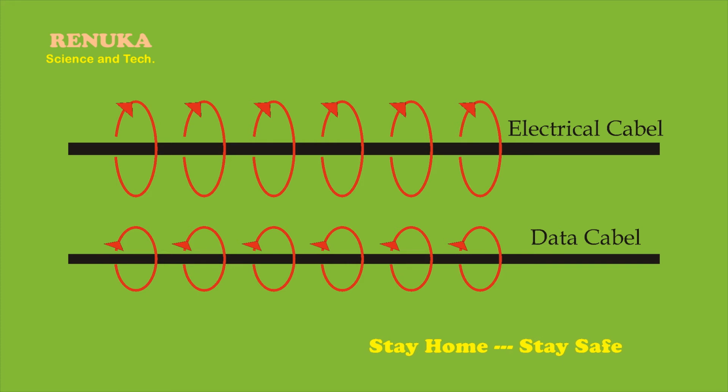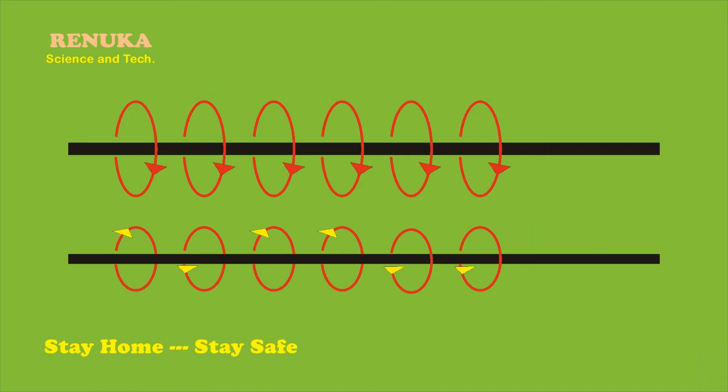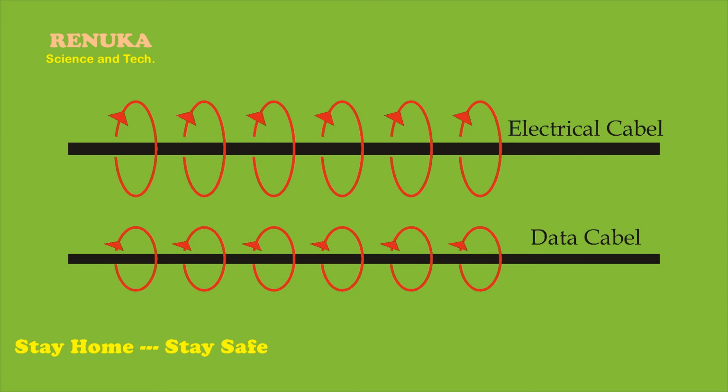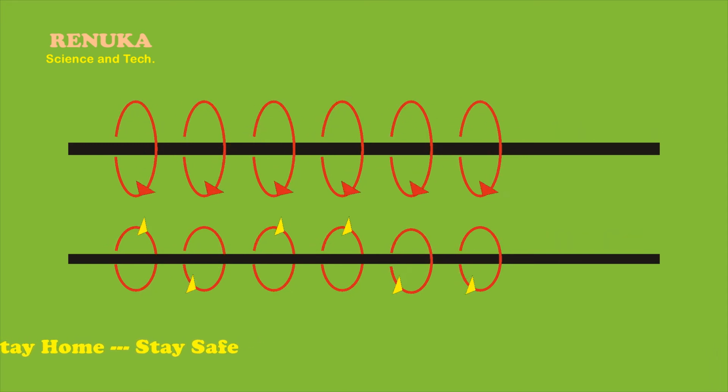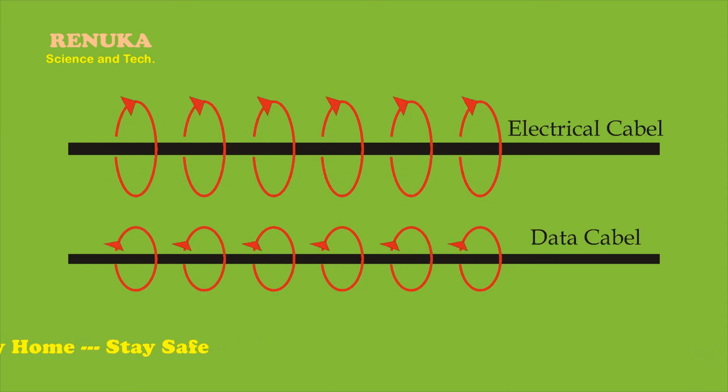Now let us move to another definition, noise margin. When these digital circuits are connected to one another, their inputs and outputs have to be connected with the use of cables or wires. Now if these wires pass through a magnetic field or an electric field, they may introduce unwanted voltage inside the wires which are carrying the digital data, and this unwanted voltage is called noise.